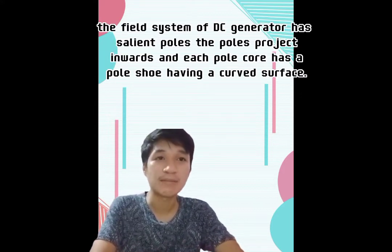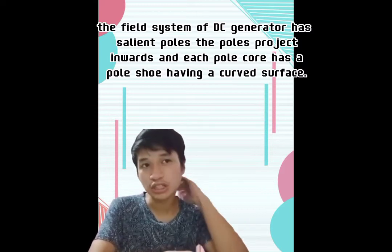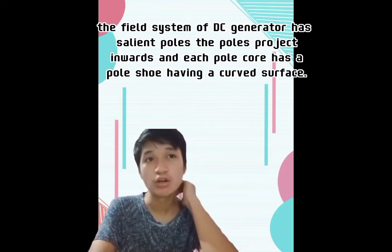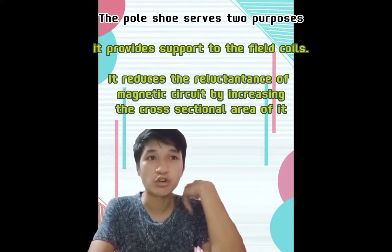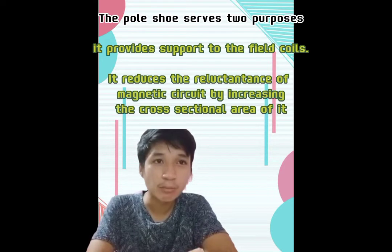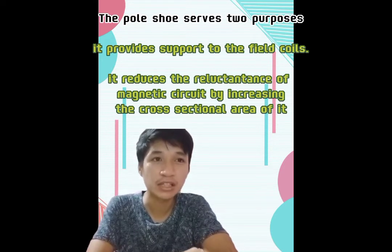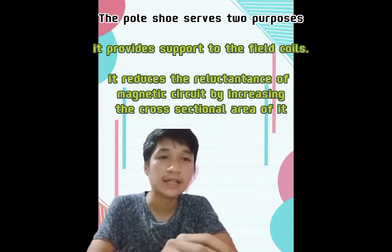The field system of a DC generator has projecting poles, which point inwards, and each pole has a pole shoe with a curved surface. The pole shoe serves two purposes. It provides support to the field coil, and it also reduces the reluctance of the magnetic circuit by increasing its cross-sectional area.